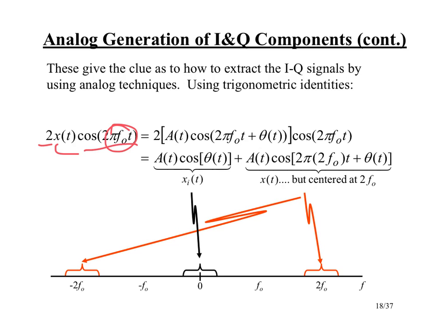Now remember, we talked about how for a bandpass signal f0 is somewhat arbitrary. If we knew what the transmitter's carrier frequency really was, then that frequency might make an obvious choice for f0. But if we get it slightly off from that, it's not a big deal. All the math still works.